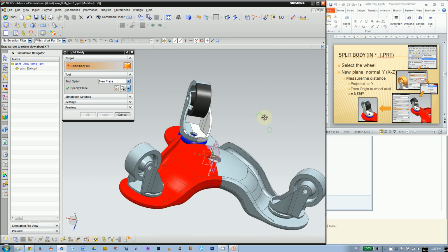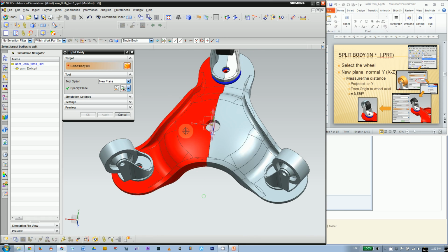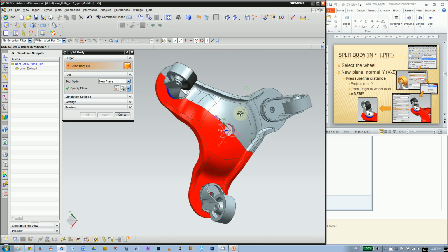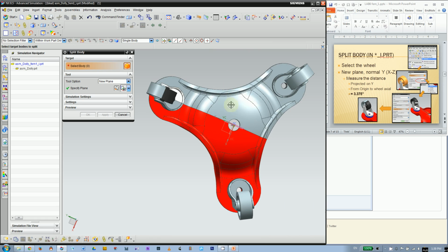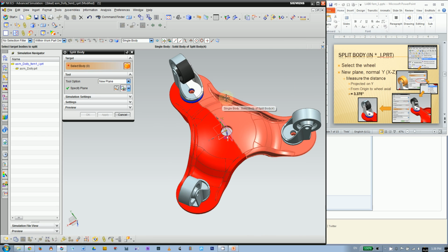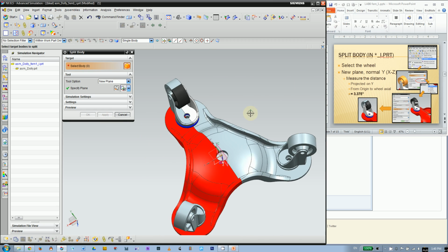Now the last step is, of course we can mesh this half and half for the body, but it's also symmetry in this direction, right? So we can make another cut here and use this. This is 1/6 of the whole body. So you can reflect this to this side and reflect that 120 degrees. So that's what we are going to do.